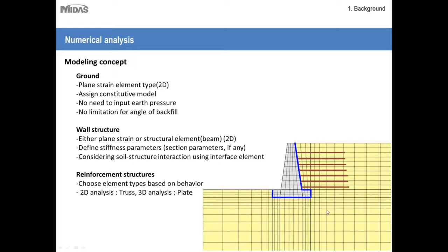So right now you can see this is just a 2D representation, and here you will see this is a single line element for reinforcement. But let's say this model was not 2D and it was 3D, so it will have a third dimension in that direction. So this 1D member will then span in 2 dimensions, and therefore this will no longer be a 1D member, it will be represented by a plate member.